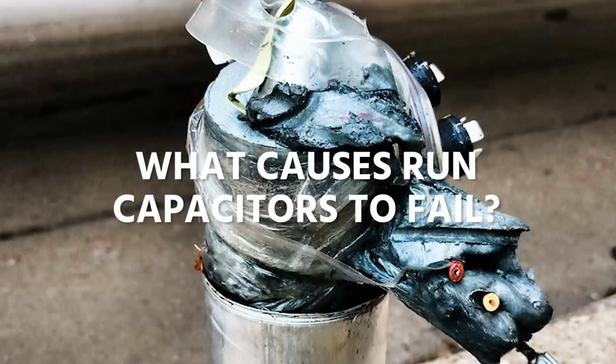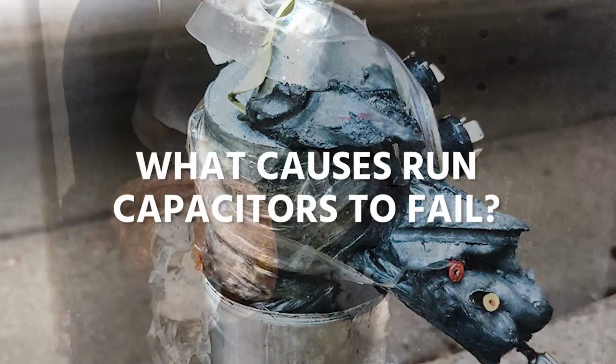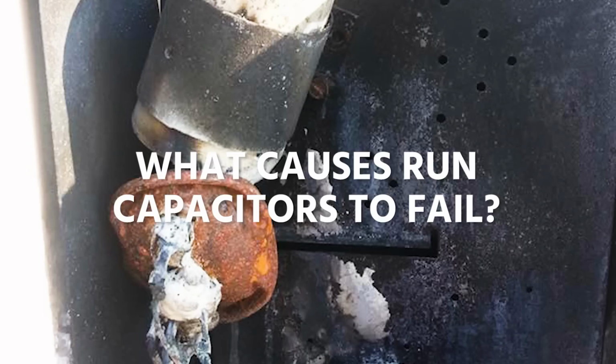So capacitors that stay in the circuit all the time, for the compressor, condenser fan motor, and the blower motor. A run capacitor doesn't have a relay in it like a start capacitor, and so it's not affected by turning it on and off. It doesn't have to come out of the circuit at a certain point like a start capacitor. So a lot of the confusion that I see when it comes to things that technicians think of as causes for failure, those are causes for failure for start capacitors, but not for run capacitors.